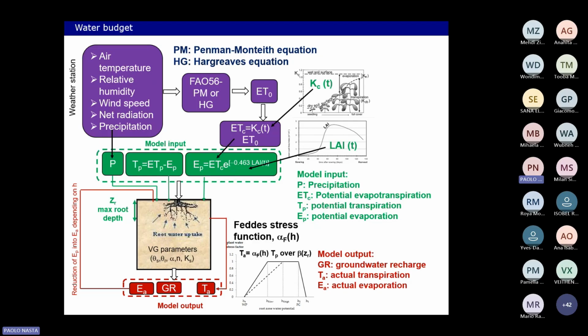So precipitation and potential evaporation will be the elements in the upper boundary condition, acting on the soil surface. The potential transpiration will occur across the root depth through the roots, so through the famous sink term, which depends on the root depth, which can change over time as well, if you have, again, an annual crop. And it has a specific root distribution.